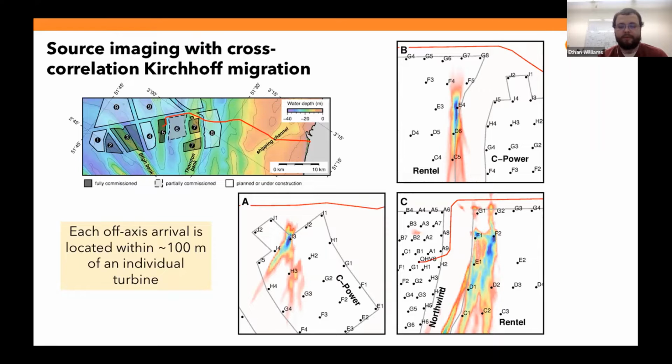If you think about forcing a building, it resonates, but it doesn't resonate forever. And of course, there's some friction within the building itself, but a lot of the energy leaks out the bottom. And that's a dominant method of damping by soil structure interaction. And of course, those waves don't just become incoherent energy, they become coherent seismic waves we can observe.